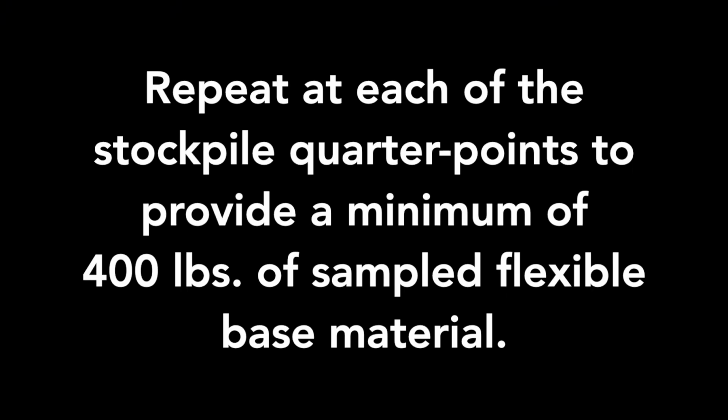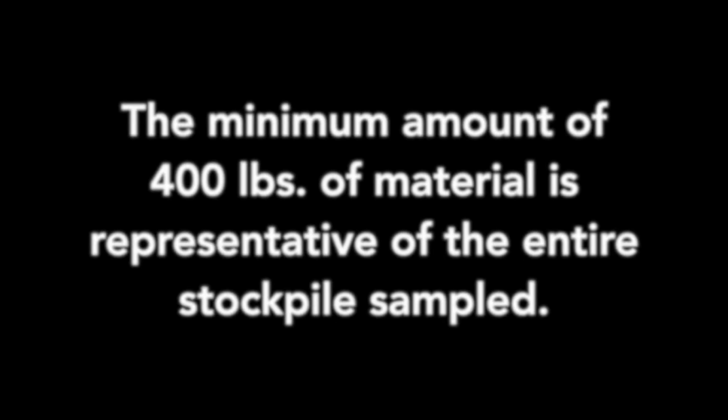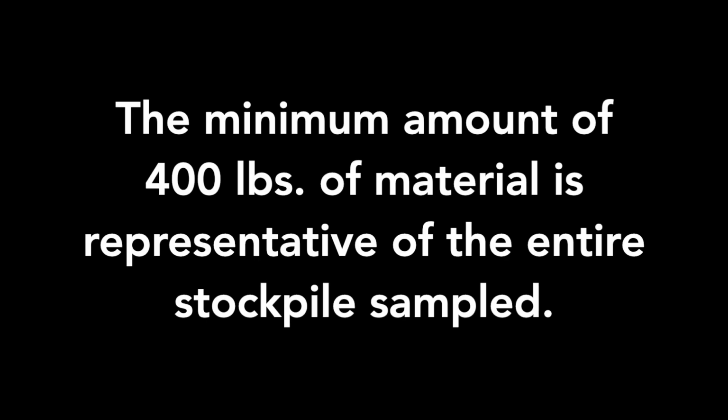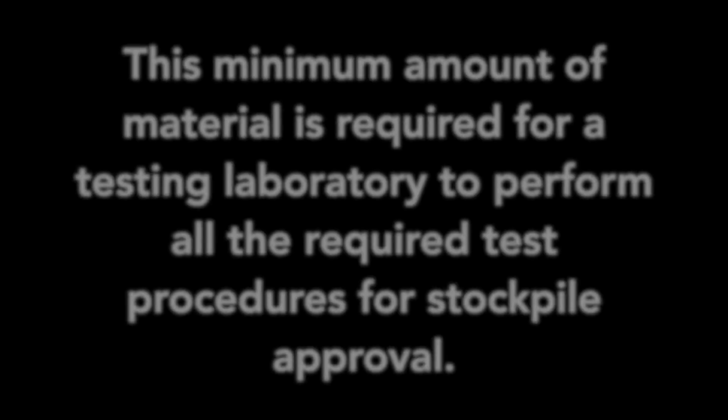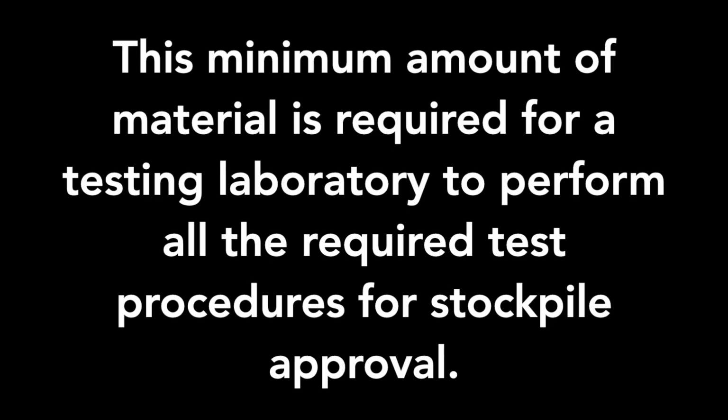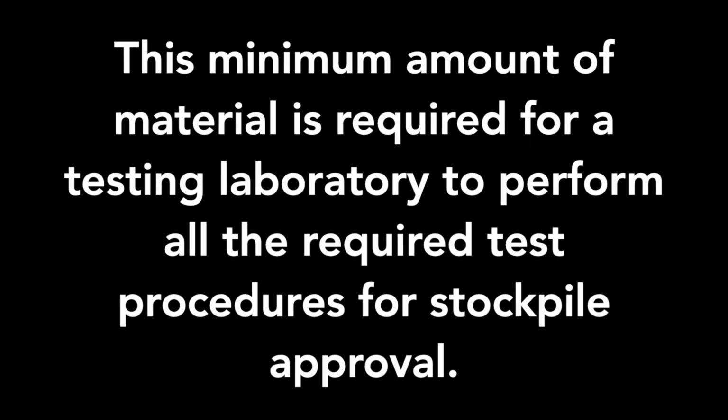Repeat at each of the stockpile corner points to provide a minimum of 400 pounds of sampled flexible base material. The minimum amount of 400 pounds of material is representative of the entire stockpile sampled. This minimum amount of material is required for a testing laboratory to perform all the required test procedures for stockpile approval.